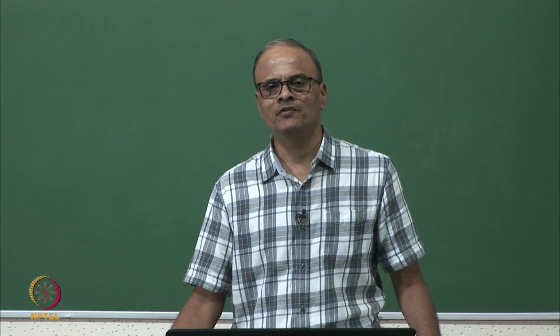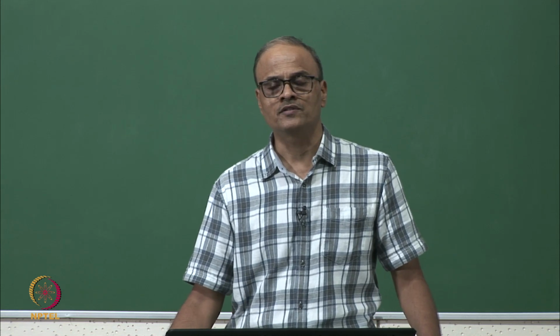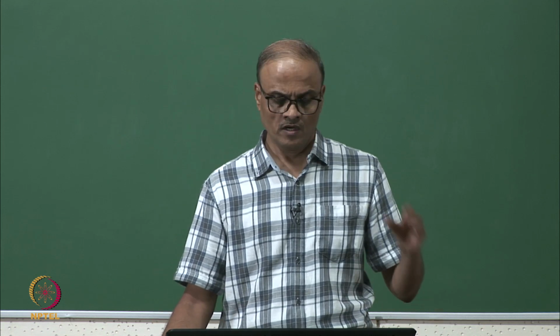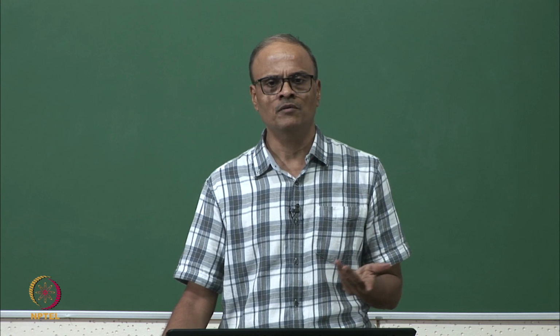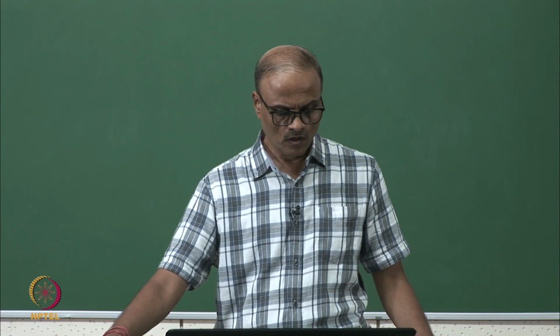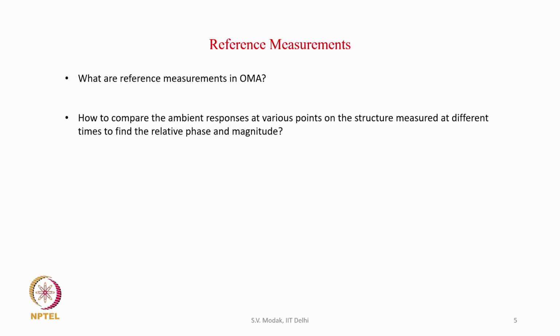One of the differences between the operational analysis and the experimental analysis is the fact that in operational analysis reference measurements are taken. So, let us try to understand what reference measurements are and why they are taken in operational analysis. So, the question is how to compare the ambient responses at various points on the structure measured at different times to find the relative phase and magnitude.